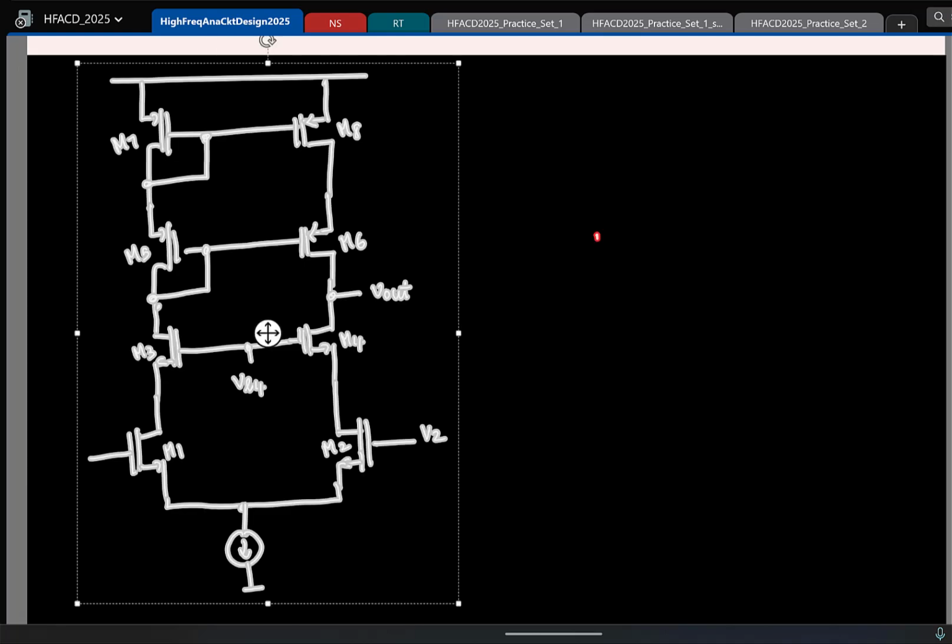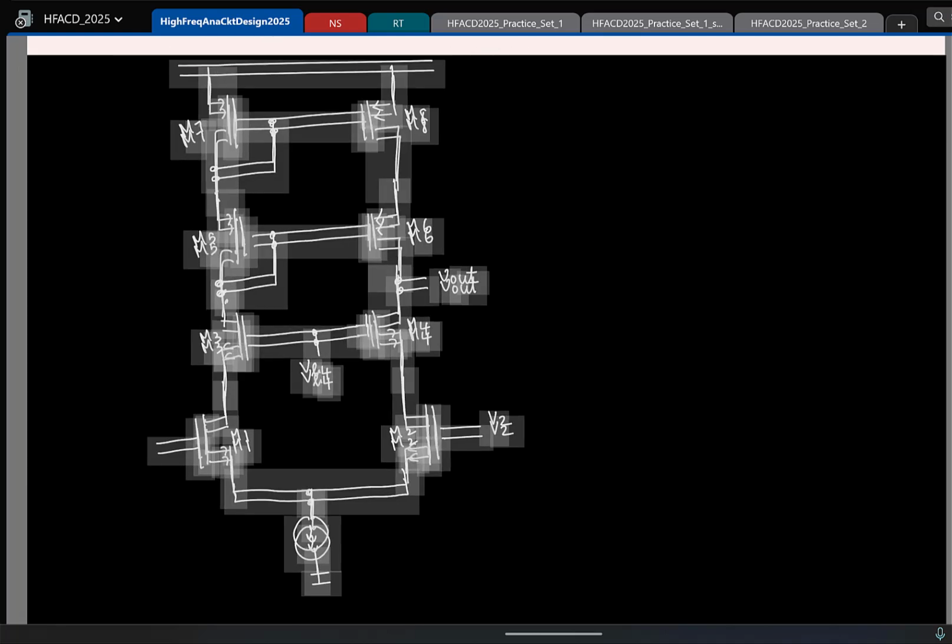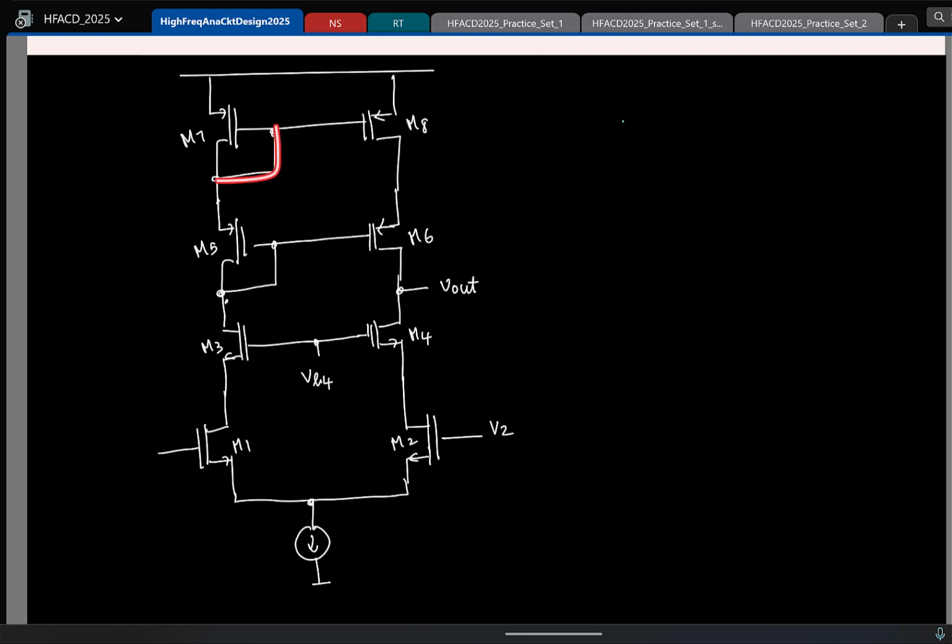The only change we have done is to connect the gate and drains for both PMOS transistors. So let's quickly look at the bias points. Let us say we apply a bias voltage VB. What can you say about the two currents now? Again, let's not do it again and again. It will be the same as I0 by 2. All the drain voltages on both sides will be the same. So then tell me, what is this voltage?